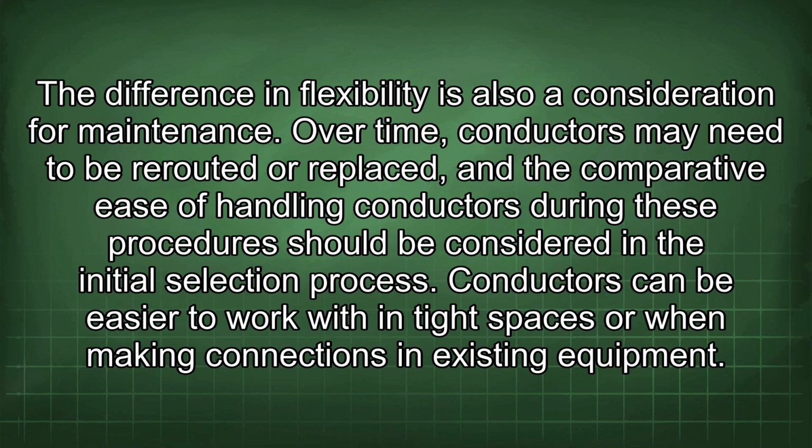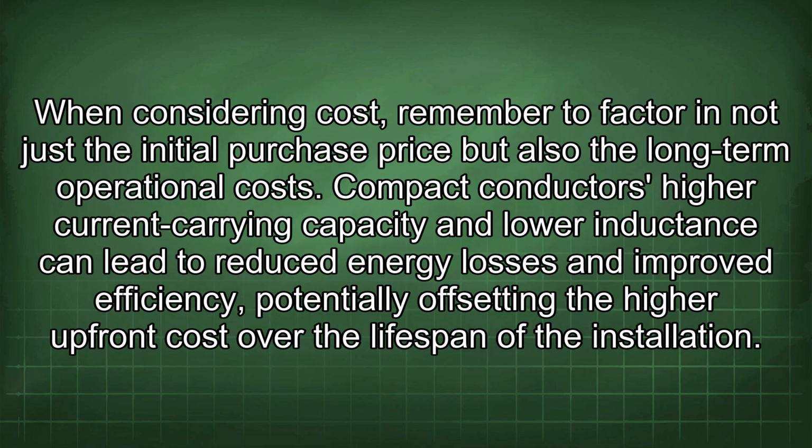Conductors can be easier to work with in tight spaces or when making connections in existing equipment. When considering cost, remember to factor in not just the initial purchase price but also the long-term operational costs. Compact conductors' higher current carrying capacity and lower inductance can lead to reduced energy losses and improved efficiency, potentially offsetting the higher upfront cost over the lifespan of the installation.